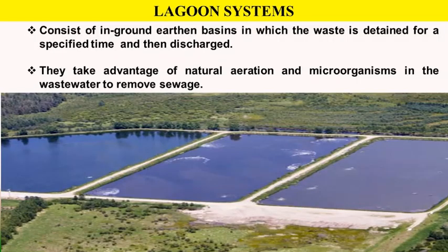Tertiary treatment or disinfection is done for the purpose of destroying the harmful pathogenic microorganisms, which are disease causing germs. It is done through chlorination, ozone, ultraviolet light or hydrogen peroxide. Mostly chlorination and UV arrangement is preferred for the purpose of use.